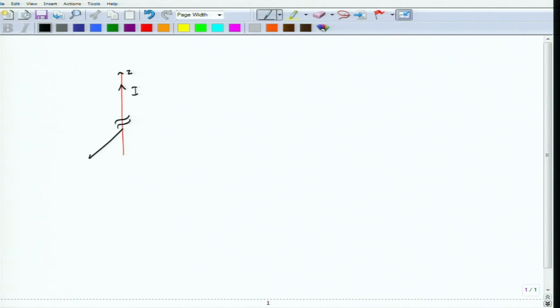The wire, because of this there would be a magnetic field, and what we are interested in is to find the magnetic field that surrounds this wire using Ampere's law. So, remember Ampere's law: consider any particular contour C, and if you integrate the tangential magnetic field over the contour, that must be equal to the total current that is enclosed by that loop or the contour.